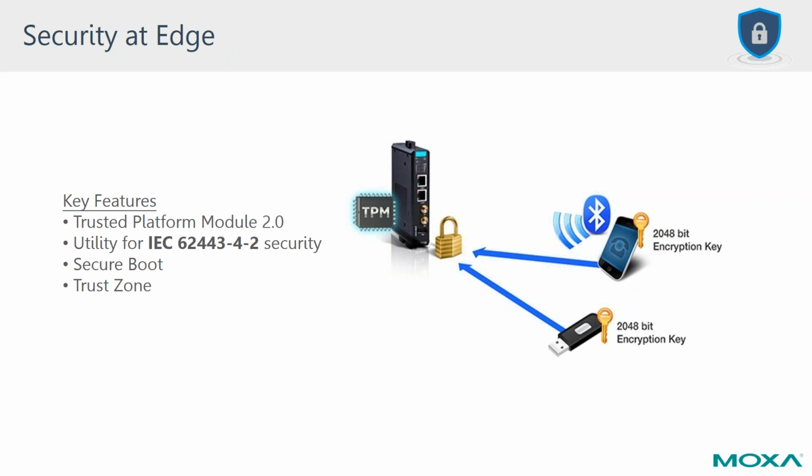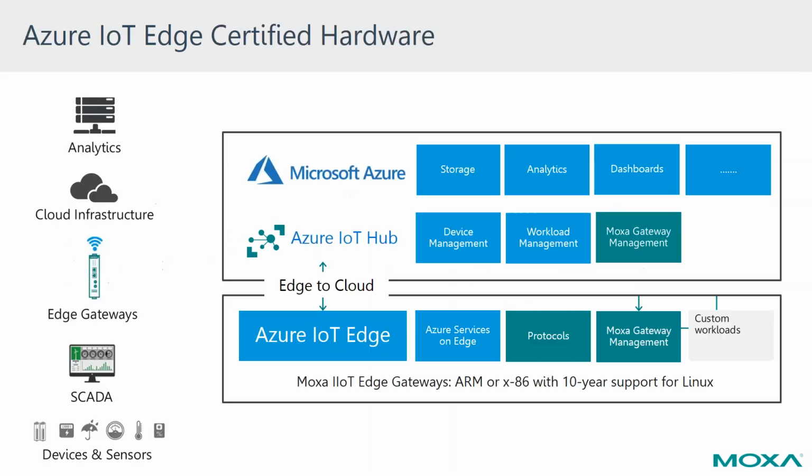And then finally, some of the newer technology coming out, things like Trust Zone or Root of Trust. This is actually taking the encryption and security, not just to a dedicated chip like TPM, but actually to the core ARM processor. And so some of the new products that are being released, we have newer NXP dual core ARM processors that allow us to start implementing Trust Zone and Root of Trust into the hardware itself.